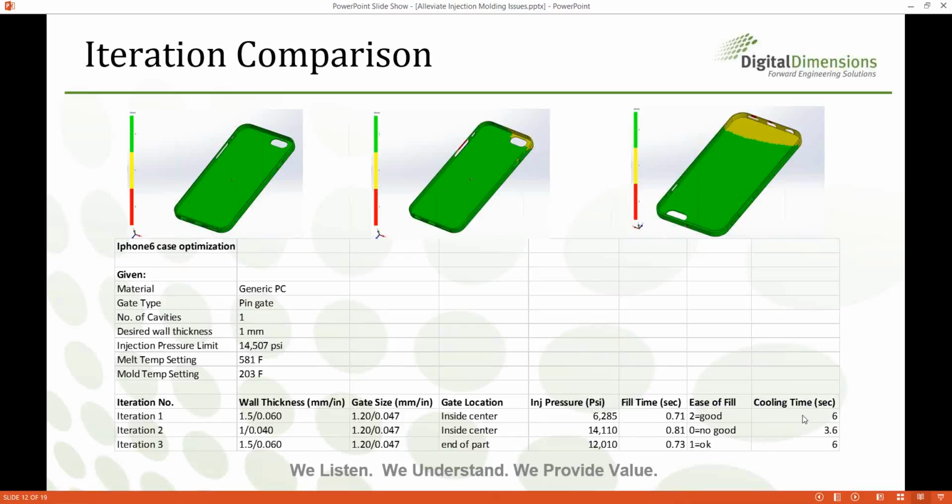So basically what I'm looking at in plastics is telling me what my pressures are, how thin I can thin this part up to and still fill it safely, and what machine I'm going to have to use. So depending on what options you have there, that's definitely some good information to have when you're trying to design a part, right?